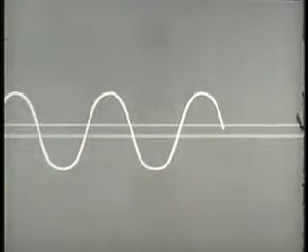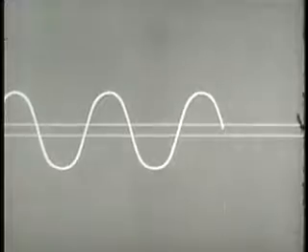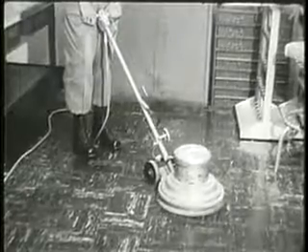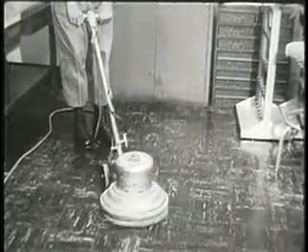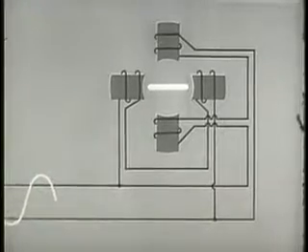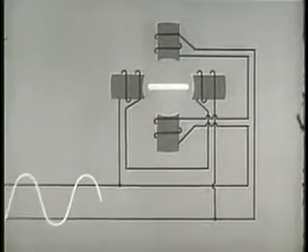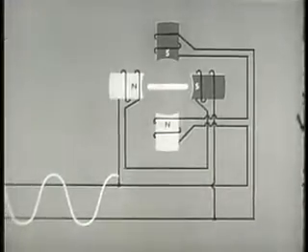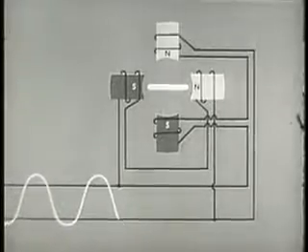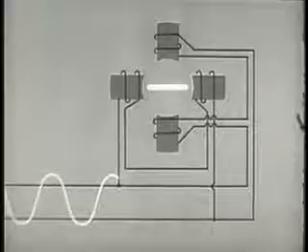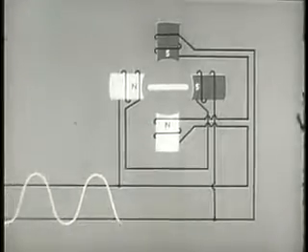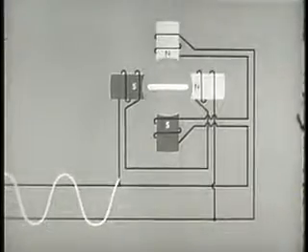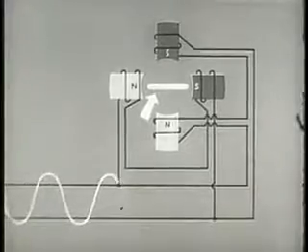The most common type of current available in most sections of the country is single-phase AC. For that reason, single-phase induction motors are widely used for many and varied purposes. In the single-phase induction motor pictured here, the single AC output energizes both sets of poles simultaneously. There is no phase difference in this arrangement, and so the field will not rotate. As the cycle of the AC wave changes, the poles pulsate alternately. But since there is no relative motion, the rotor will not turn.